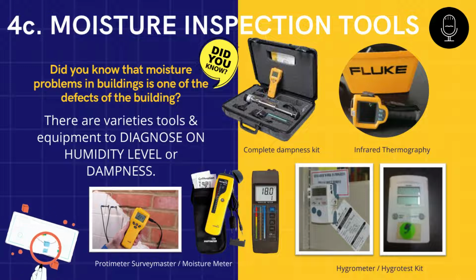Additionally, building surveyors use moisture kits that contain all the necessary instruments in one convenient package, also known as a complete dampness kit. A hygrometer is an additional tool that can be used for similar purposes. An accurate reading for the room's relative humidity and temperature can be obtained using this tool.